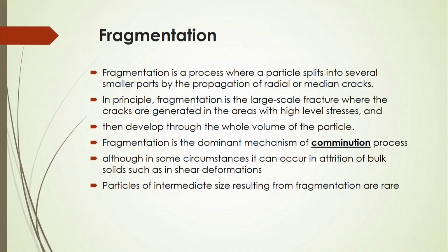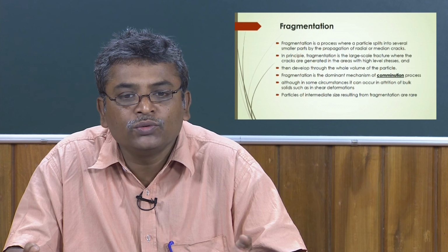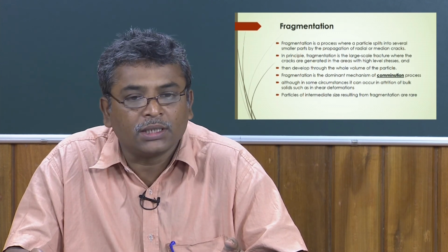Fragmentation is a process where a particle splits into several smaller particles by the propagation of radial or median cracks. In principle, fragmentation is a large scale fracture, where the cracks are generated in the area with high levels of stress and develop through the whole volume of the particle.